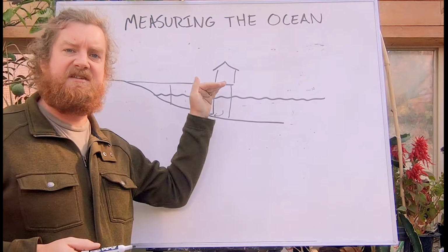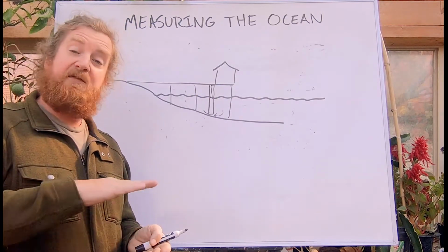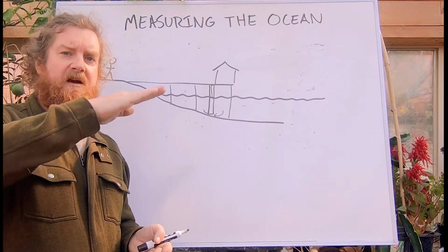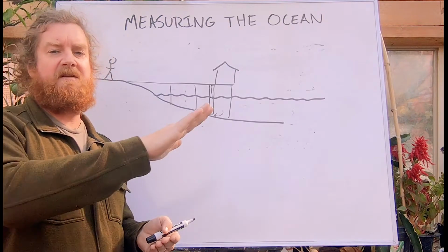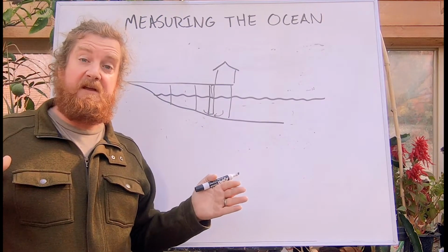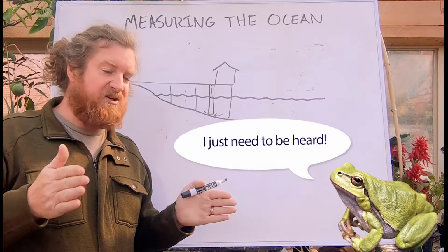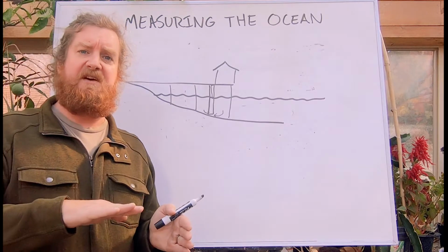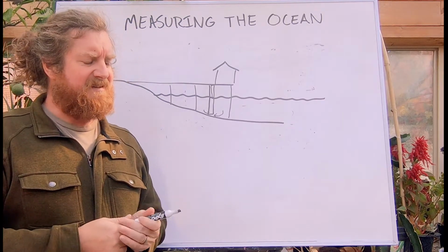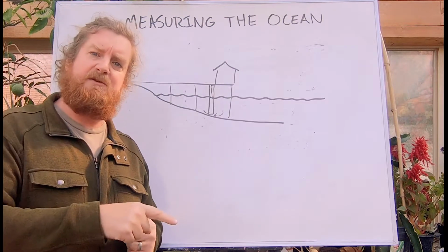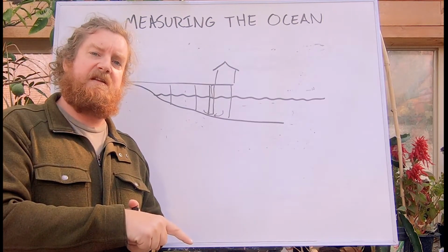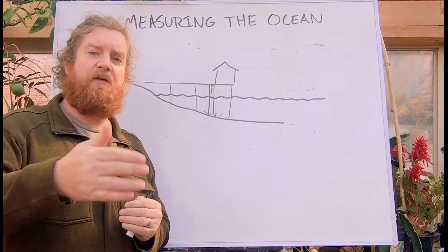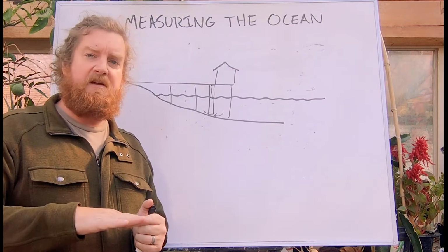And then to solve for mean sea level at this observation location, this is what we would call a tidal observation station, we could look every hour and mark the level of the water. Right, so tides are going to go up, tides are going to come down, storms are going to come in, storms are going to go out. If we took 20 years of data and we had hourly measurements of sea level, we could actually just average that, right? And that would be our definition of sea level. So it's not necessarily like there's anything that you could just point to and say, this is the definition of sea level. You have to collect a lot of data, compile that data over a number of years, and that could be your sea level.